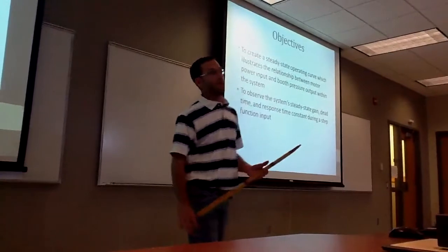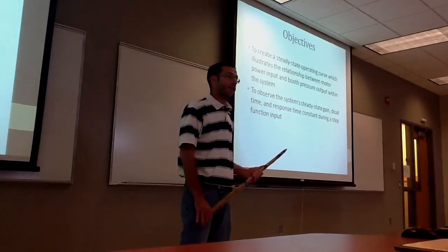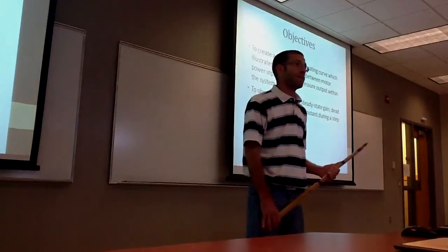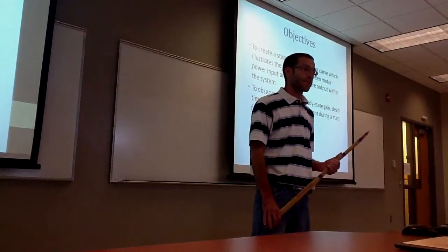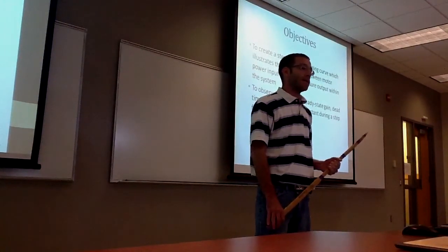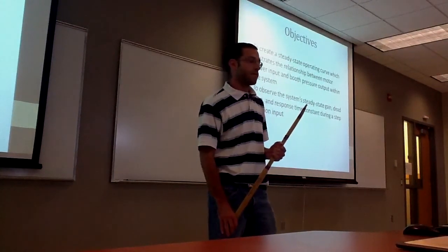So the objectives of our experiment were to create a steady-state operating curve, which can illustrate the relationship between motor power input and booth pressure output within the system, and also to observe the system's steady-state gain, dead time, and response time during a step function input.